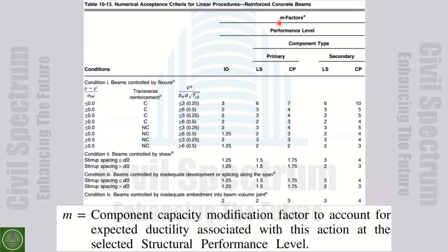But we are talking about an existing building. One element is good, one element is bad. One element is 1.25, one element is 10. One element is allowed to have 1.25 times its capacity as force in elastic analysis, this much damage, but one is 10 times.